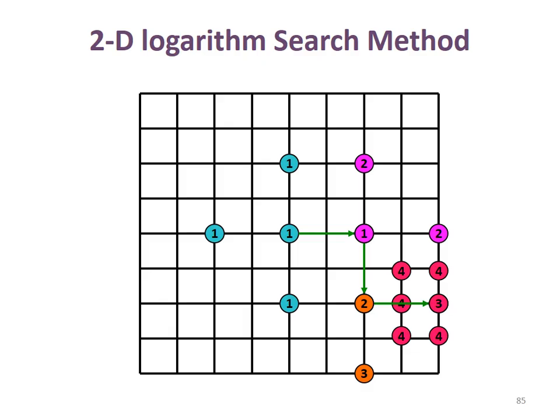Okay, then we choose the minimum mean square error from these 5 candidates. In this case, we have the minimum value by the gray position. Okay, in the end, this is our final target. We assume by this fast algorithm, this is the smallest one among all search regions. So we can record the motion vectors from this position to this position.